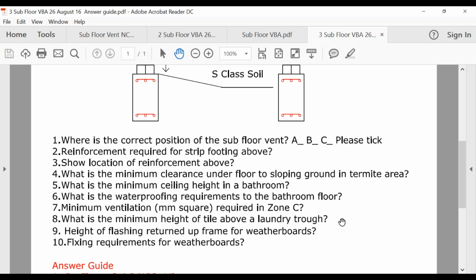Yep. And it has requirements for rafts and slabs. And it's showing a sectional of a strip footing, and it's showing 50 mil. Okay, it's funny because from memory, somewhere it talks about if it's protected or unprotected, and I thought that if it was protected it was 40 mil. But that's going from memory without actually having the book in front of me.